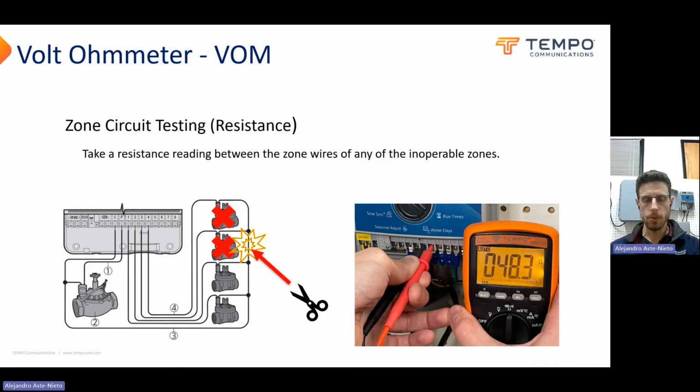This will show you the amount of resistance introduced from this wire, which again is not going to be much, the amount of resistance introduced by this solenoid, which is going to be 20 to 60 depending on the manufacturer, and the amount of resistance from this solenoid added to it. So we're basically doubling the amount of resistance from one solenoid, and then again, negligible resistance here back on this wire.